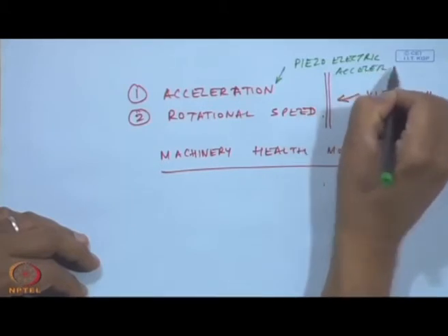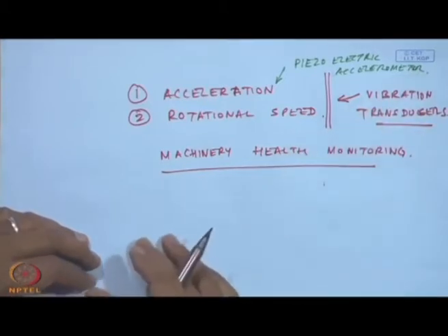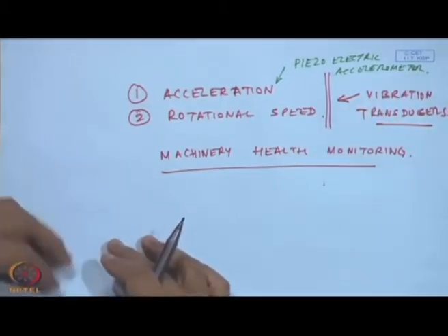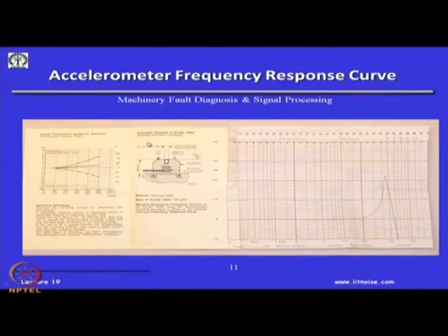Before the piezoelectric sensing elements were used, people also used strain gauges instead of piezoelectric crystals to measure the seismic accelerations. And this is how a typical chart of an accelerometer will look. This is the frequency response and these are the resonant frequencies, and then what are the methods to mount the accelerometer, and what are the voltage and charge sensitivity as a function of temperature, etc. This is typically what you will find in any of the accelerometers which we purchase.